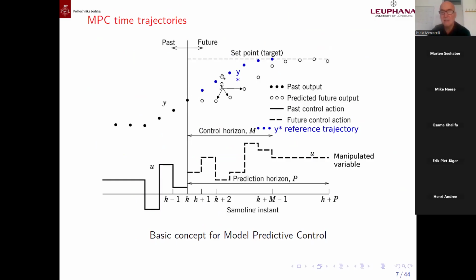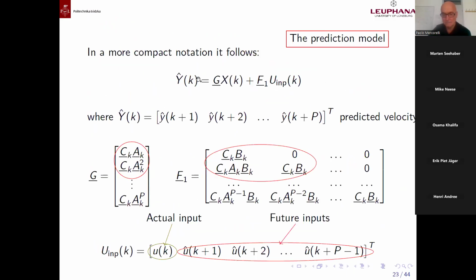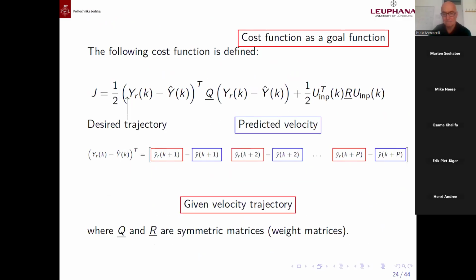This value here, this value here, this value here is our trajectory to be set, to be tracked. We can set in the vector. This means YR minus YK here. I forgot. Oh, no, it's correct. I see now the hat, transpose, multiplying a matrix of the weight. Now we can consider in particular this matrix also. Multiply again the vector, realize the error squared.